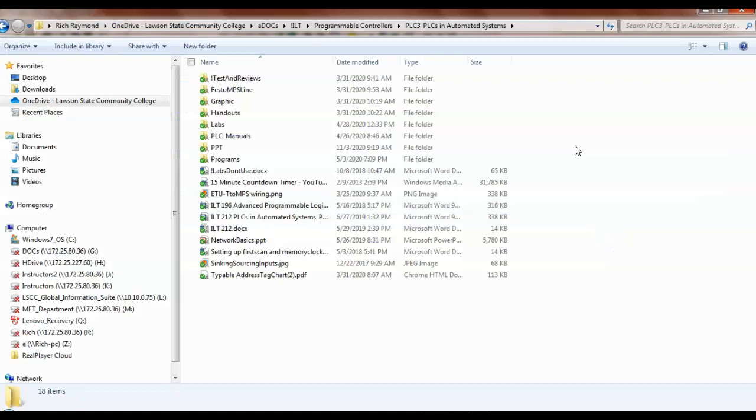The one thing that we'll use them for in here is what we call internal relay. These are guys that don't need to turn on the light. They don't need to energize a solenoid. They don't need to turn on the compressor. They don't need to communicate with the outside world. They're just in there to make decisions. And like I said, in motor controls, we call them control relays because all their contacts are in the control circuit. None of them are in the power circuit. They're in the control circuit. They're just in there to make decisions.